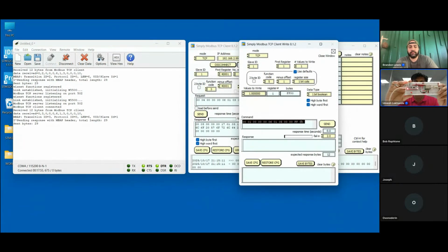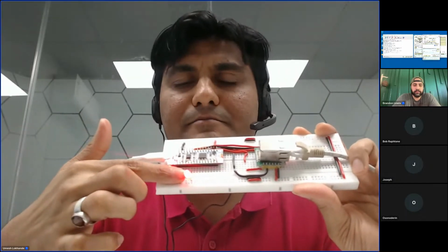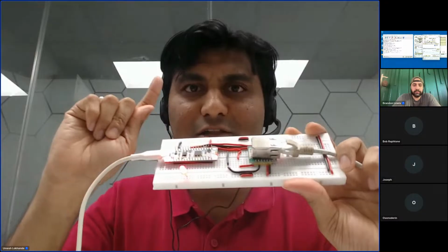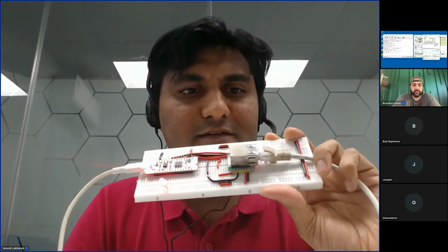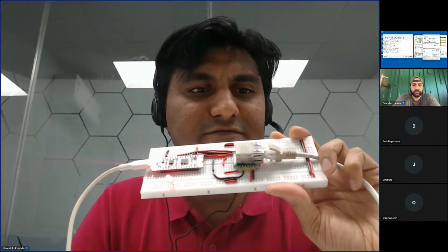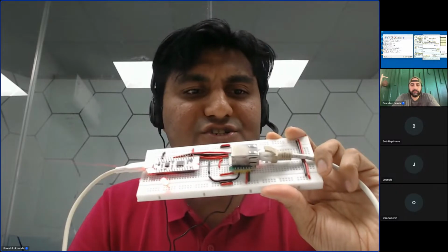Look at the hardware on the web camera. I hope you can see. When I click the send button, you see the LED light up because we write the value 1 onto the coil address 1. And you can see we receive coil 1 status changed 1, right?